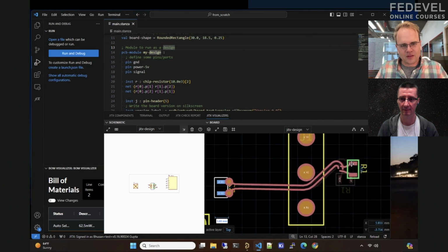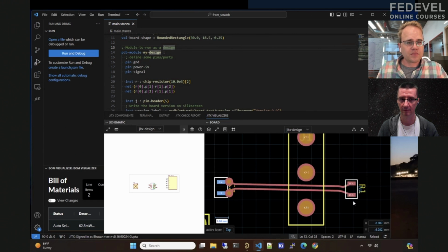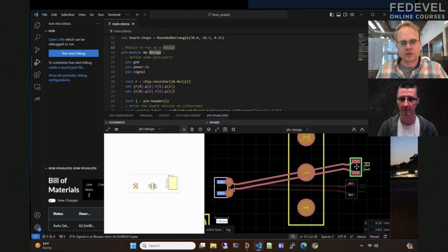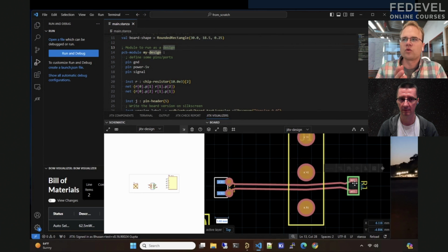So this autorouter, for example, you notice it's curvilinear, right? Everything's curved by default. And you've also given up some control, like you're not clicking out the exact path. The reason to do that is because we can then put perfected signal integrity geometry directly down on your board without you having to do it manually. And this is really helpful for higher frequency interfaces like PCIe 5, 30 gigahertz now.